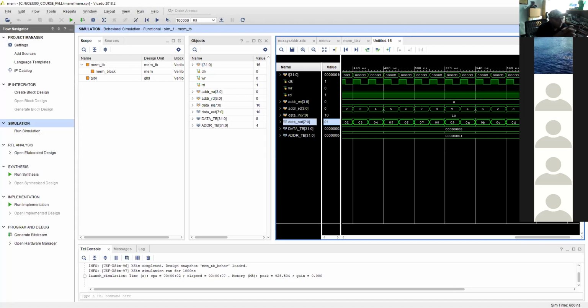We made mistakes, some of them intentional, some of them not. And then we developed a test bench. We added to the test bench multiple things that we already learned before, which is a forever. We learned also how to use the define for defining the time step for the clock. And then we started having a for loop inside the initial block for iterating things faster.